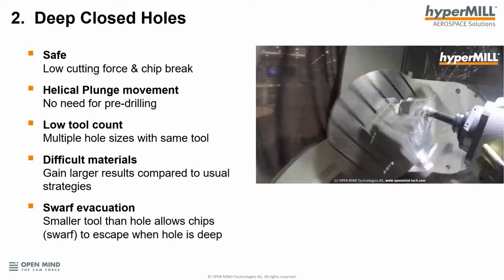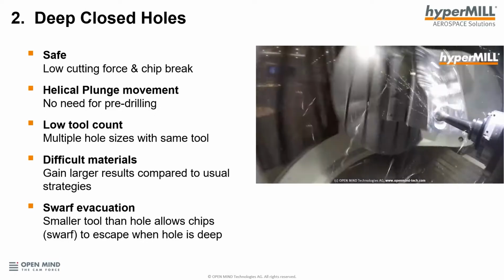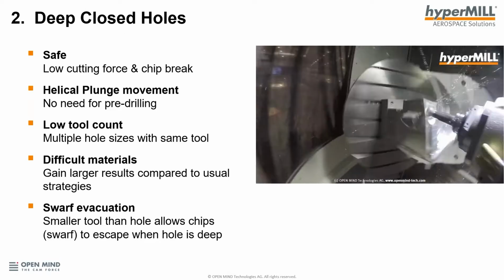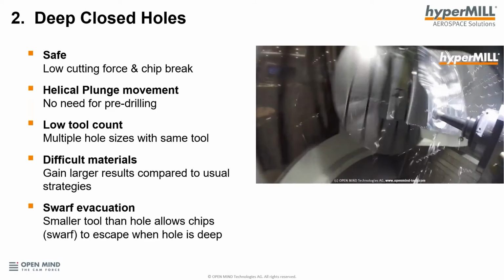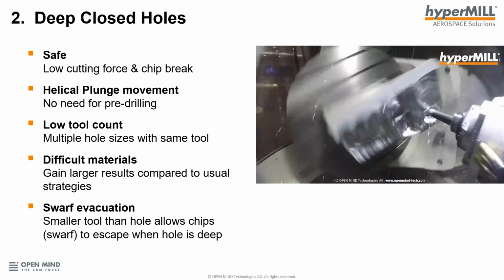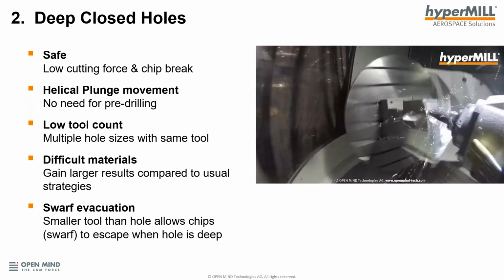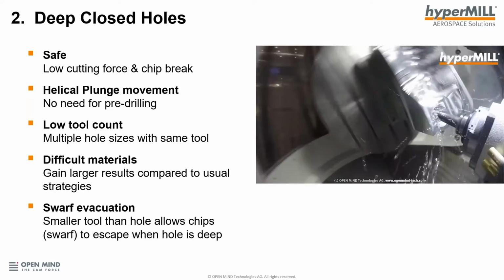The second topic I want to look at is these closed pockets. This is a technique where we're programming helical movement into the part. The tool is slightly leaning forward, so no need for pre-drilling. You can go straight into the component.